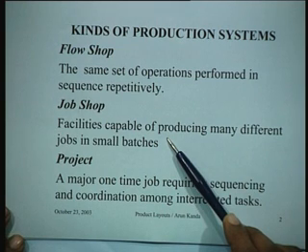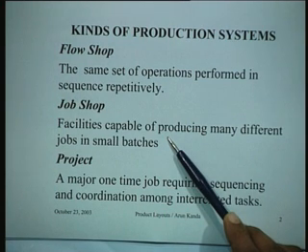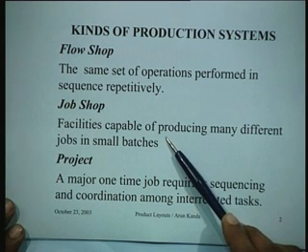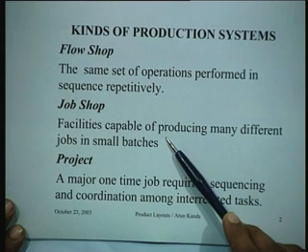So what really happens in the job shop is that the flow pattern is quite complicated, material handling costs are pretty high, and when you are designing layouts for such job shops, you are talking about the design of process layouts which can accommodate the variety of products that you make. That is what we saw when we were dealing with both the systematic layout planning procedure of Muther and also the computerized layout planning packages which are there for handling such types of systems.